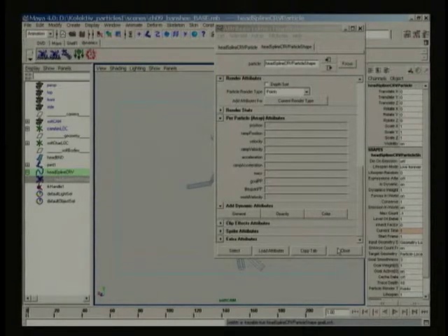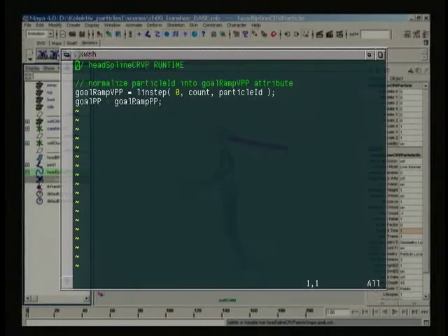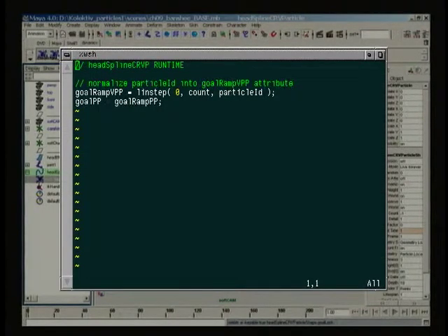Fortunately, these softbody particles are sequentially ordered from first to last, first being closest to the character's head. This means I can use my particle ID attribute as a way to look up a value in a black to white ramp. I first need to normalize the IDs so they're remapped to all lie between 0 and 1. I'll do this in my runtime expression.